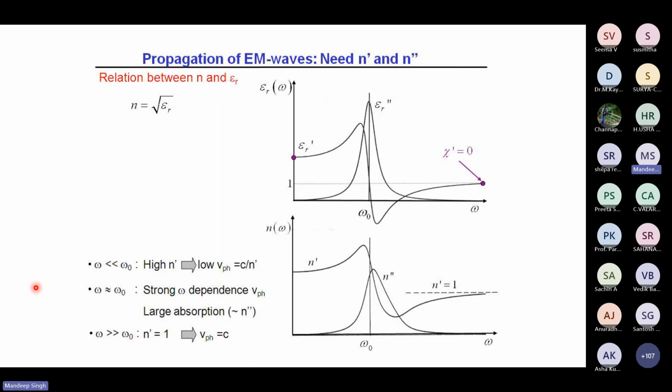You know that the permittivity is dependent upon the frequency. If you plot the permittivity with respect to angular frequency, you will get this type of plot, with real part and imaginary part. The imaginary part is nothing but your losses. These days we have software and databases, so we simply put the name of the material and we get such graphs.